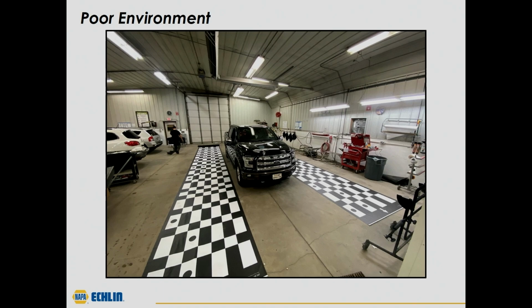This is going to be too bright for it to actually calibrate properly. And on the right side, it's going to be hard to see in the picture, but there's actually a grate to the middle of the vehicle here. So the vehicle's really not centered to a level surface. And also that target has some wrinkles in the middle. This is a failed calibration and actually does not pass.